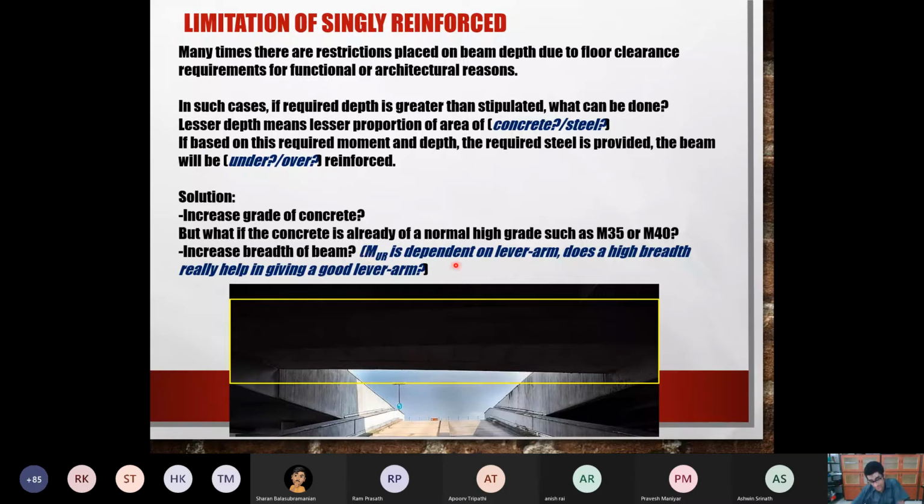Now, say moment of resistance. What I can say is, for example, the bending stress, or bending strength. Now, how do you find bending stress or bending strength? Strength of materials approach, mechanics of solids. How do you find bending stress? Formula. Sir, M by I equal to sigma by Y. M by I equals sigma by Y, or M equals sigma I by Y. Correct? Yes. Sigma I by Y.